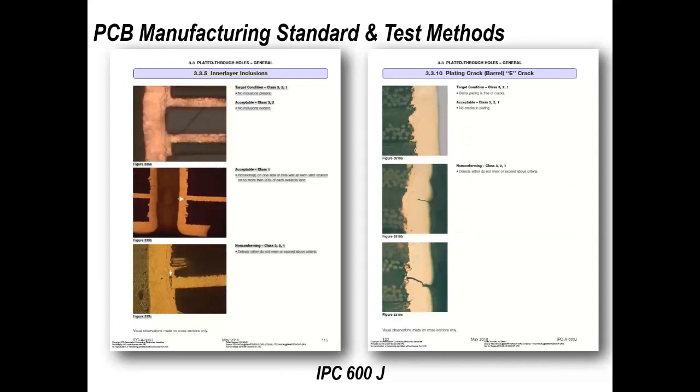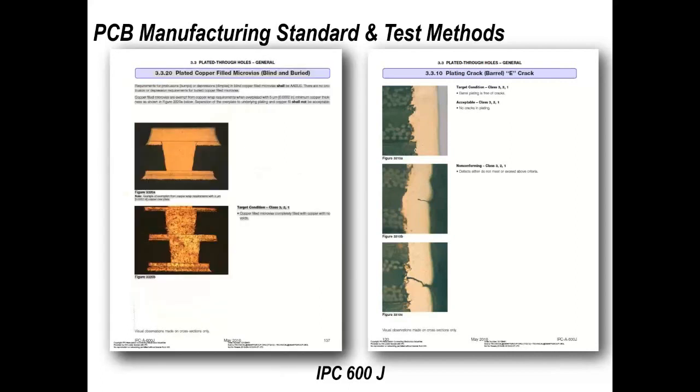So in the example I show you here, you've got cracks in the copper, which may or may not be after some form of thermal cycling or thermal shock. You might have tested the board to see whether it will live up to the standard that you require, and you're doing a before and after microsection to look at the robustness of that assembly.